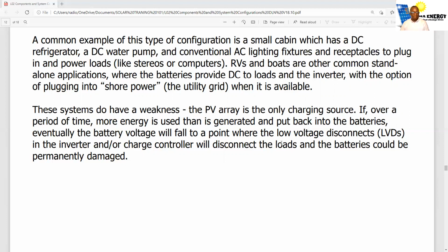Now you have to charge that battery. So that's one of the problems we are facing in Africa and Liberia. People are using the battery to 100%, so the battery dies so fast. The battery should be able to go for years, at least 8 years minimum. People are using the battery to 100%, running it out. Then we come and say we have a problem.